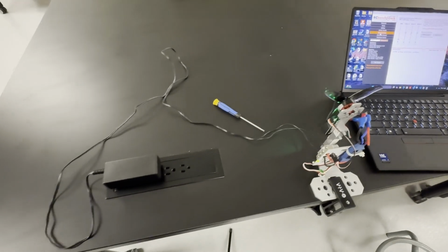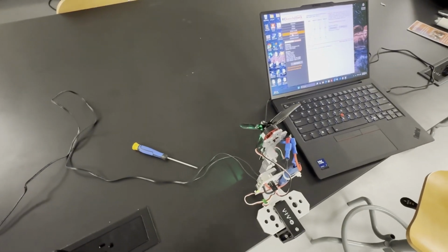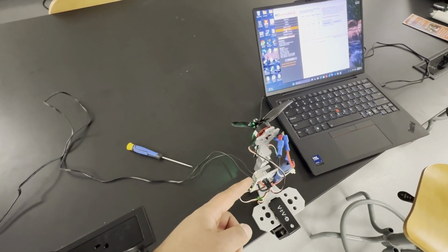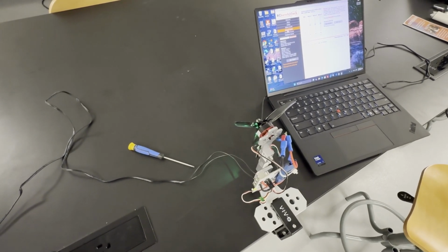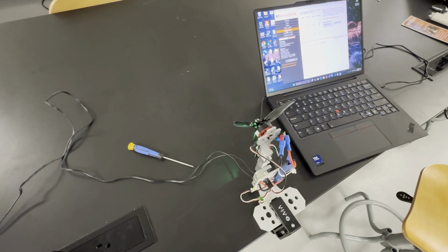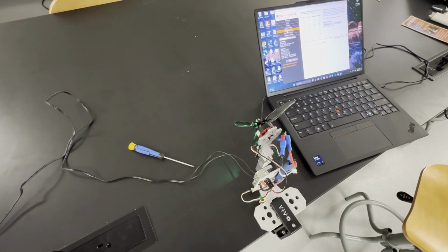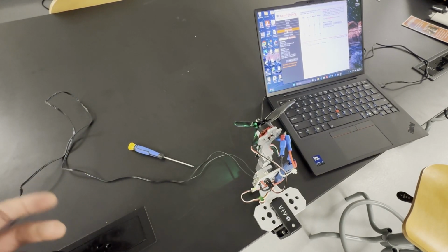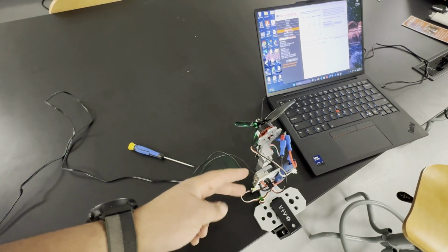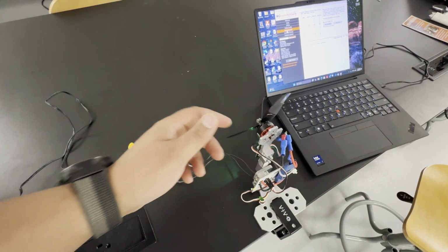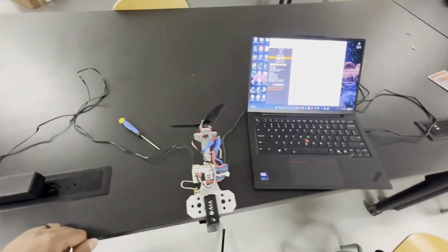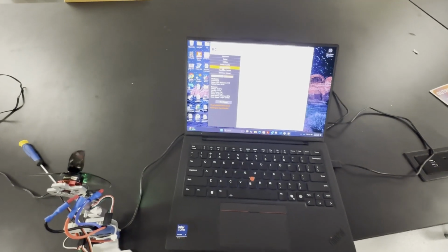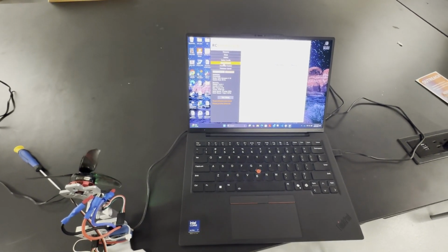The power supply connection can be tricky. You can see there are two wires. One of the wires goes to the plus, the positive port, and the other wire goes to the negative port. You want to make sure that these wires are connected correctly. How do we check that? It's pretty simple. If you connect them and this green light comes on, it means that you have the correct connection. If it doesn't come on, you don't have the correct connection. Okay? Then when you connect the USB, you have to open this RC Benchmark software.